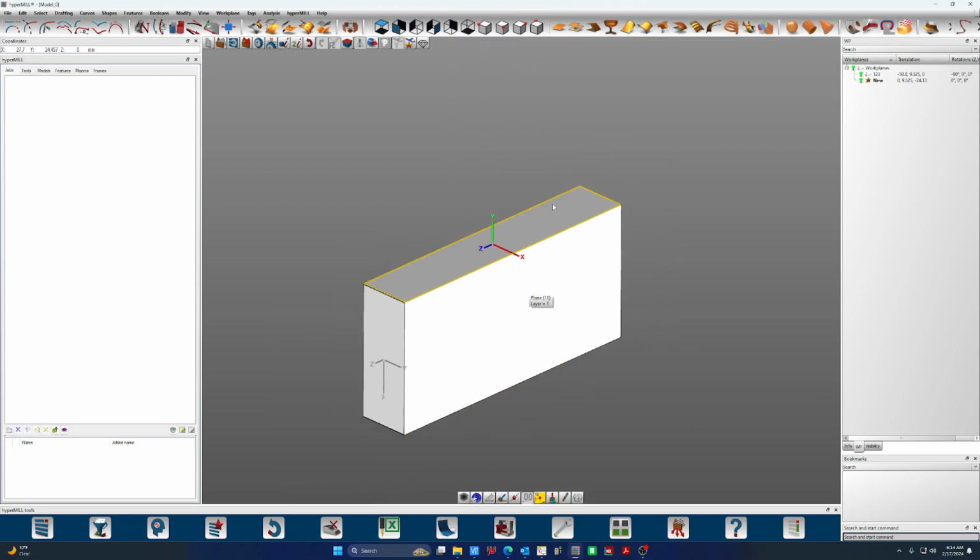This is going to be exactly what it sounds like, all native to your world coordinate system. Now, one of the beauties of hyperMILL for me is that CAD and CAM do not care where your world coordinate system is. Everyone has gotten models from a customer that are part of an assembly, and they are existing somewhere way out in space.